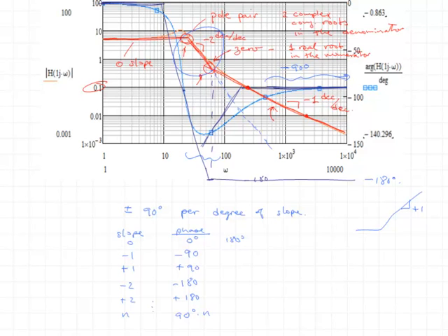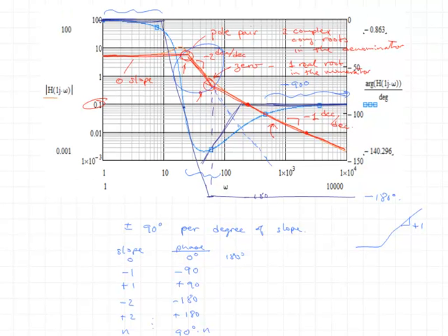So the approach we're going to use, and I realize this may seem a little foreign and confusing, and that's okay. We're going to come back and look at some examples, but I wanted to give you a big picture view first of what this technique will look like, and let you know that we are going to work on being able to construct this magnitude response curve, the red one, by first identifying the different breakpoints, the poles and zeros, and the asymptotic magnitudes that accompany those,